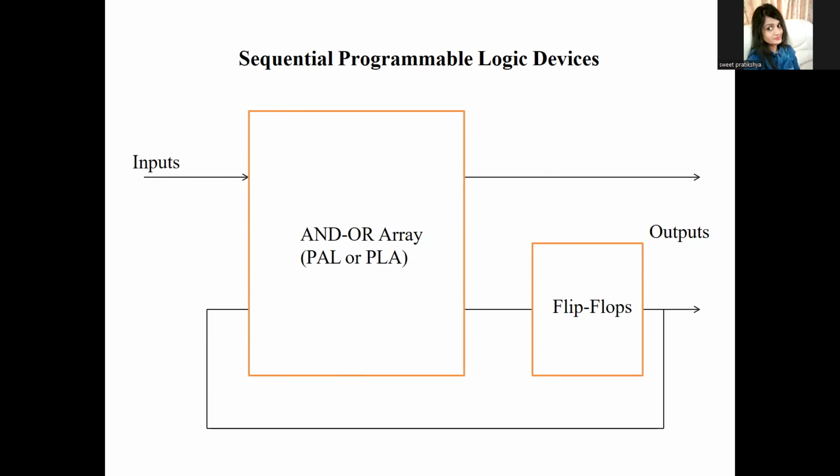In the flip-flop we have the S0 state, S1 state. In the register we have S0 state, S1 state. So these states are retained in the SPLD devices, which makes them usable for finite state machines, that is Moore machines. So this contains a number of states, and these are used for making state machines, counters, and memory-based logic. So these devices output values based not only on the current input but also on the past state, just like sequential devices.